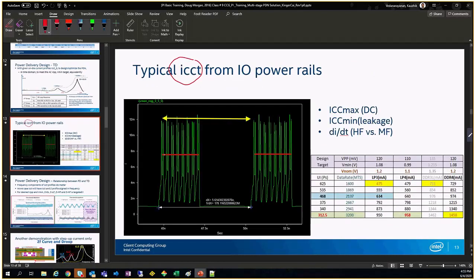It has an average value of 8 milliamps, but the value is constantly going from 12 milliamps to 2 milliamps. Imagine it's going up and down, up and down. So instead of providing a 1 amp current, we will hook this up as a current source, which I will show you how to do in SPICE. How do you hook up a profile like this? Then we will study it.